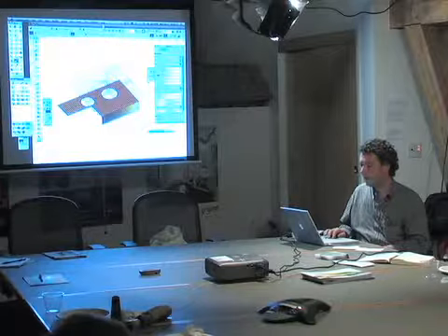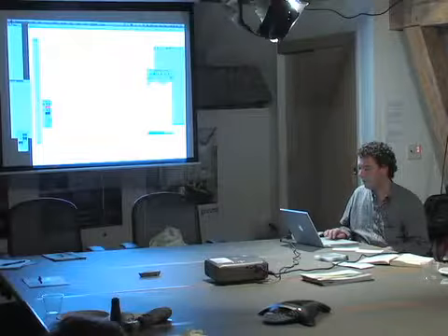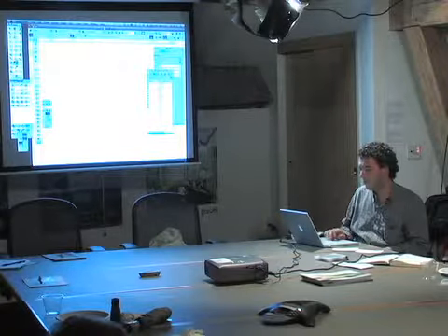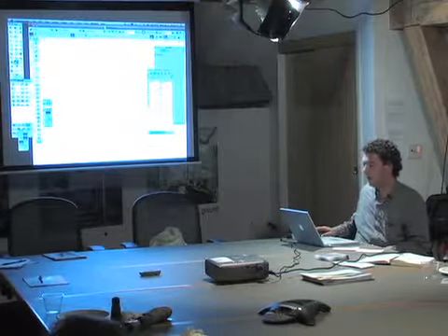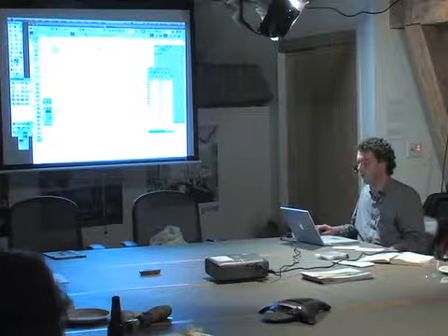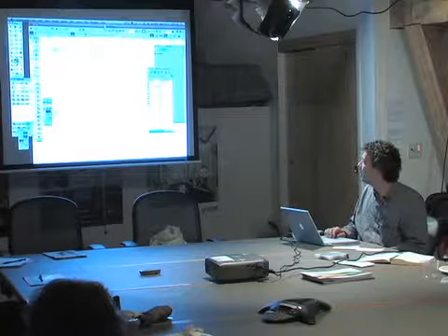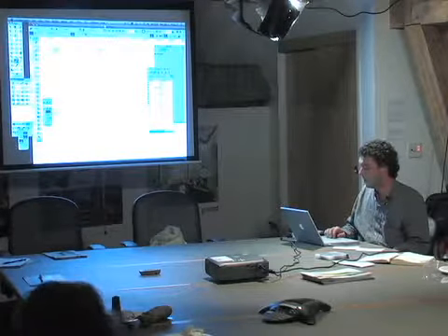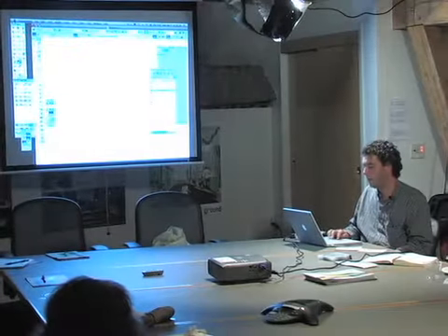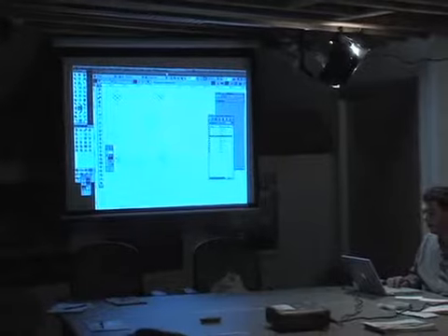One other thing, I don't know if this happened in 2010, was the design layer viewports came in, where you're able to reference a viewport within your drawing. So now I've got this one page set up. This is different layers within this page. I've set up over here different layers. I've got my model layer, which I'll work in, but I've set up different layers here for my left rear view, my rear view, my right rear, a couple sections.